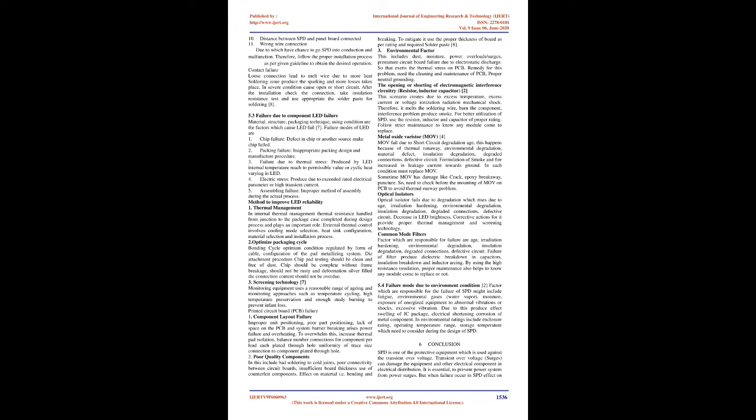Methods to improve LED reliability. 1. Thermal management. In internal thermal management, thermal resistance from the junction to the package case is handled during the design process and plays an important role. External thermal control involves cooling mode selection, heat sink configuration, material selection, and installation process.